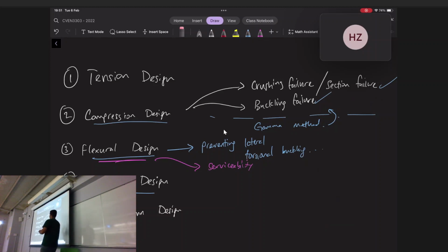So there is a topic within flexural design that teaches you how to calculate the deflection of a beam due to the loads and the restraints or whatever that are applied. And of course, you've got to check that against a sagging limit, right? So in most structures, you'll have a sag limit, which is length divided by 250 or length divided by 500, whatever it is. Basically that is the code requirement for the maximum sag you can have for a beam. And that comes under the flexural design chapter. Okay, serviceability is really, really important.